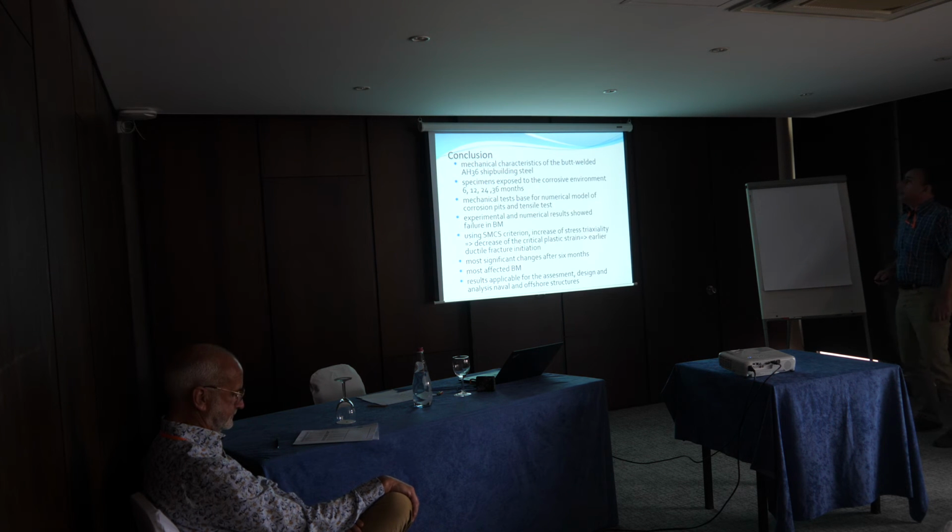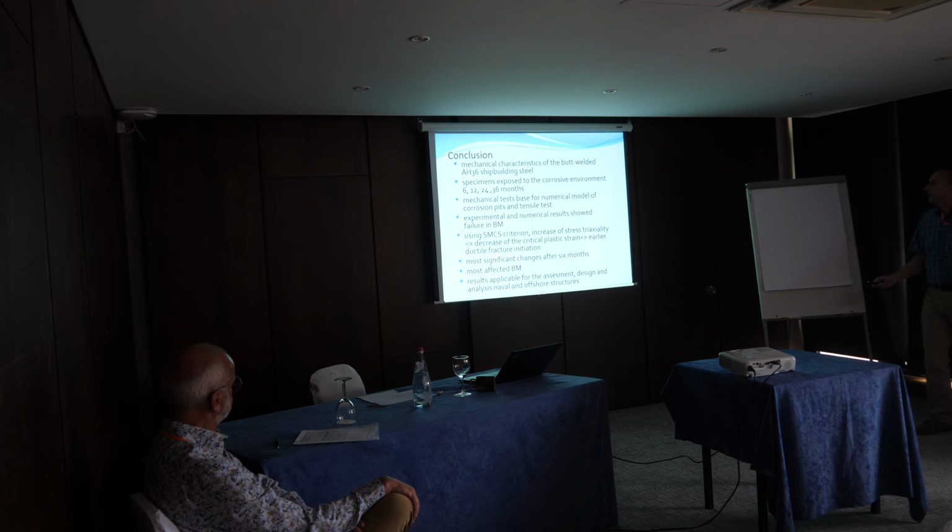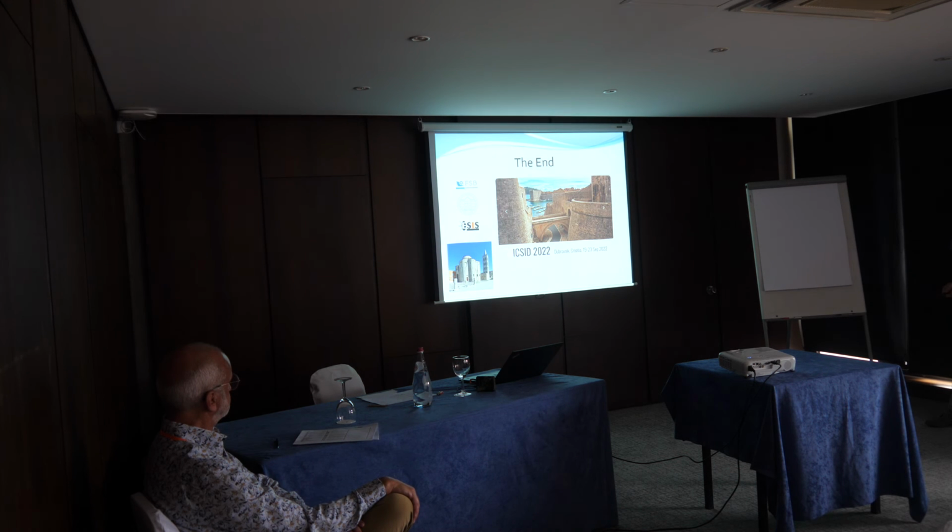At the end, the conclusion. The main conclusion is that using this criterion, we had an increase in stress triaxiality, which decreases the critical plastic strain, and as a consequence, we have earlier ductile fracture initiation. The most significant changes are after 6 months, and the most affected is the base metal. These results are very applicable for the assessment, design, and analysis of naval and offshore structures. At the end, I wanted to invite you to our Professor Bozic conference in Dubrovnik this September. That's it.